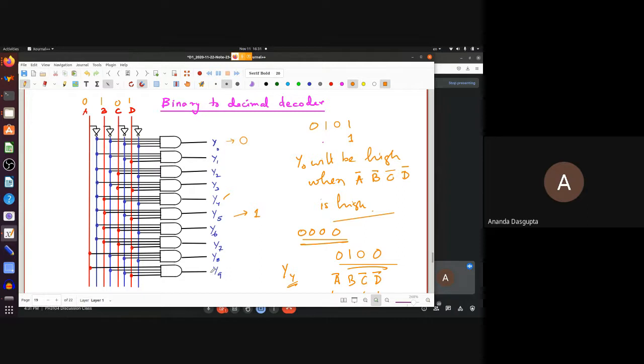And here, for example, Y9 is connected to, okay, again, reading red as 1 and blue as 0, this is 1, 0, 0, 1, which is exactly what 9, the decimal number, is. But then there's 1, 0, 1, 0, 1, 0, 1, 1, and so on, 10, 11, 12, all the way up to 15. Those extra 6 possibilities from 10 up to 15 are not being used here because we are using a binary to decimal decoder. If you had tried to build a binary to hexadecimal decoder, or binary to hex decoder, which is what people call it in the colloquial electronics language, they don't call it hexadecimal, they just call it hex, you would need 16 4-input AND gates and essentially follow the same pattern after this.